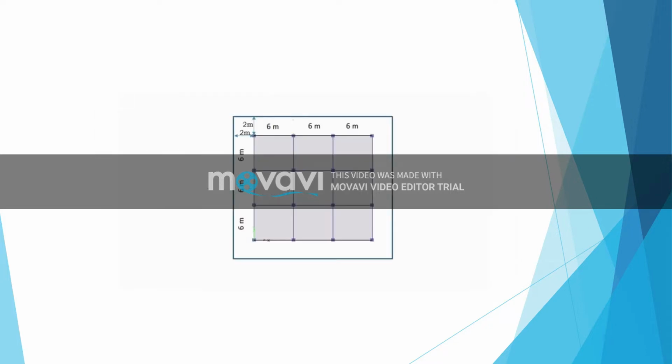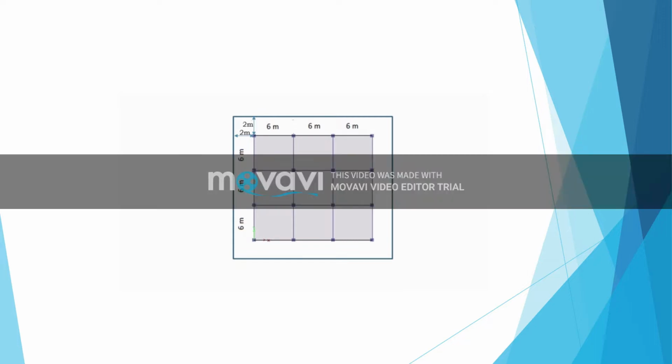Now the plan shown is the plan of the footing. The footing underneath will be extended on all sides to cover the corner columns. Let us extend the mat by 2 meters on all sides. Hence, the length of the mat on all sides becomes 22 meters. Now let us proceed forward for designing the footing in the SAFE software.